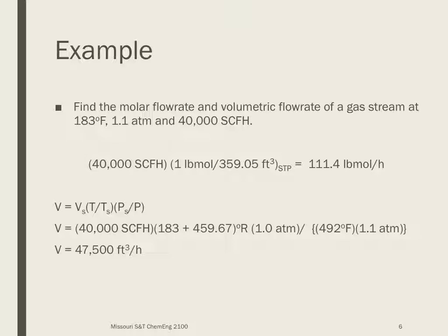Using the definitions of STP, we find that 40,000 SCFH, well, go back to the table and we see that a standard cubic foot, or a cubic foot at STP, 359.05 cubic feet is the same as 1 pound mole. So that creates for me a conversion factor. So I'm treating this as if it's a conversion factor. And so therefore, using this relationship, I find that 40,000 standard cubic feet per hour is equivalent to 111.4 pound moles per hour. So that's my molar flow rate.